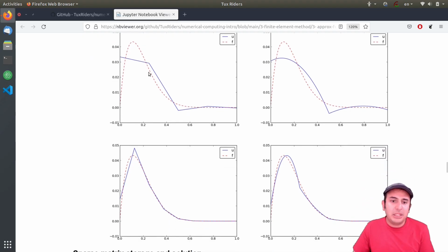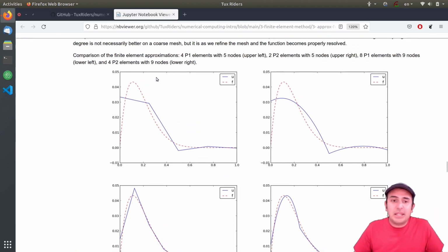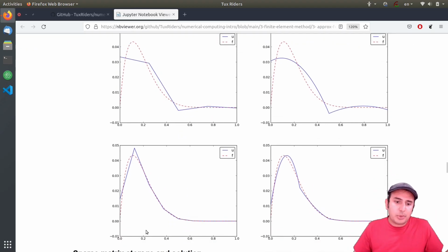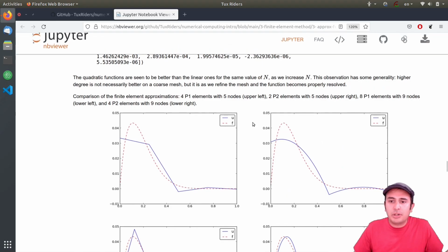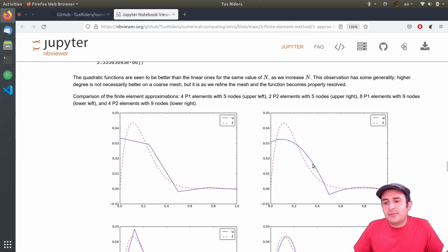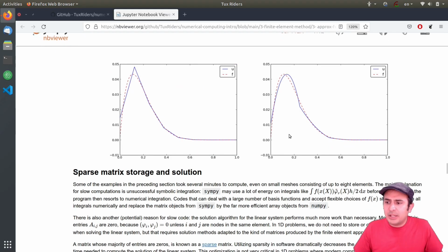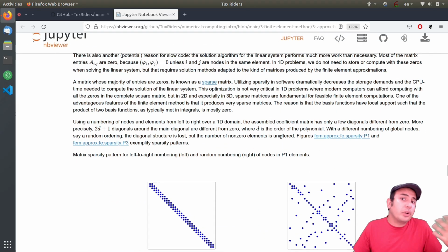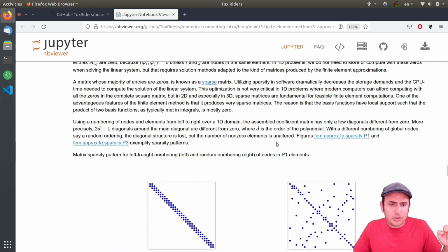And then here we have different approximations. In this case, there are P1 values, where we use only linear elements, linear basis functions. Now we can use more accurate terms. So linear basis functions, it is this approximation with correct values for boundary condition, and this is for quadratic basis functions, meaning the P2 elements. And we can have also higher order elements, and I will show you later.